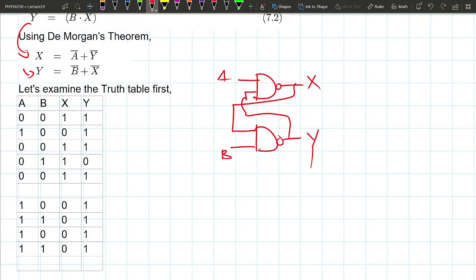I'm going to check the other side, make sure this gate also gives me a valid output, right? Since Y is 1, right? 1 and 0, right? Because A is 0, negate it, right? That gives me 1 as the output, okay? So 0, 0, 1, 1 is a valid state for this flip-flop, okay? Okay, we'll see what happens, okay?